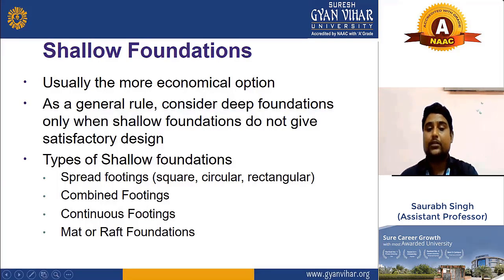There are four types, as you can see here, spread footing. One more thing I would like to clear here: foundation and footing are both the same thing. Sometimes we call it foundation, sometimes we call it footing. Both words are suitable for shallow and deep. Generally we don't call a deep foundation a footing; we only use the word footing for the shallow foundation.